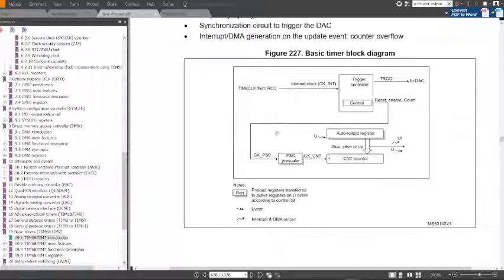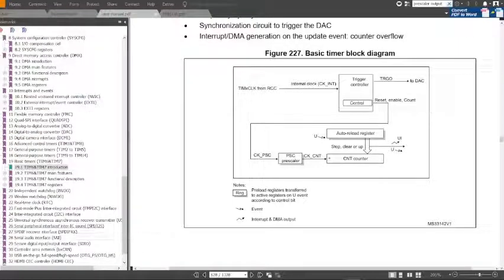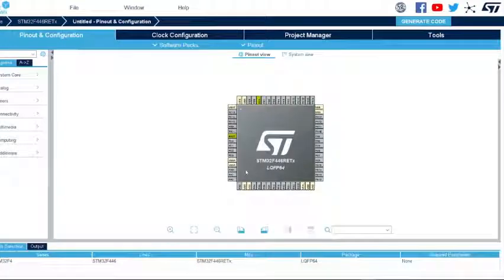Let's say the 16 megahertz that you have fed in here, it will scale down that 16 megahertz clock depending on your prescaler in such a way that it would count the counter, and you also have a predefined value right here. If it matches the counter, it would trigger the interrupt. So go ahead and explore that in your datasheet.